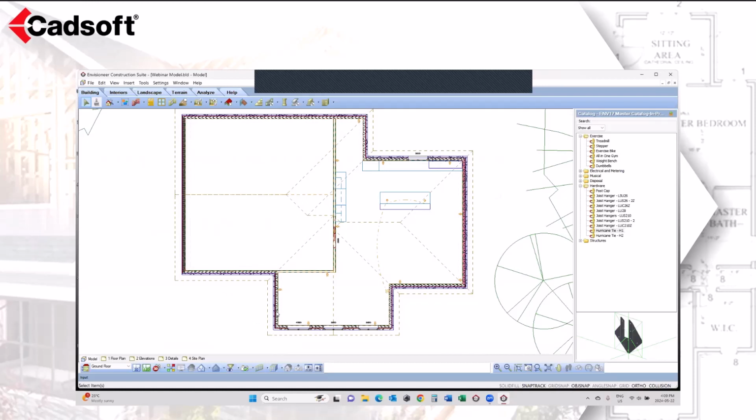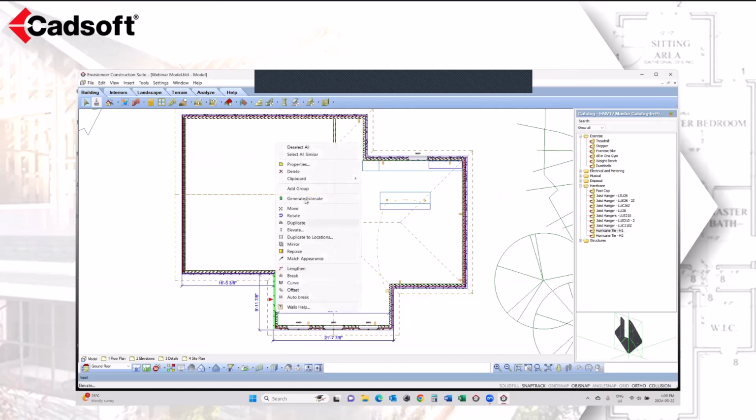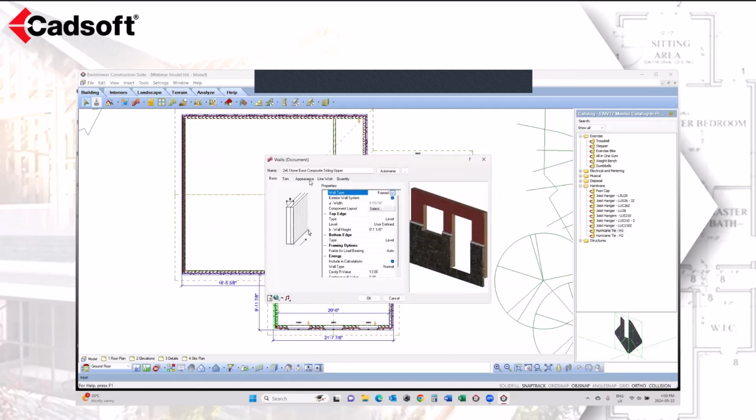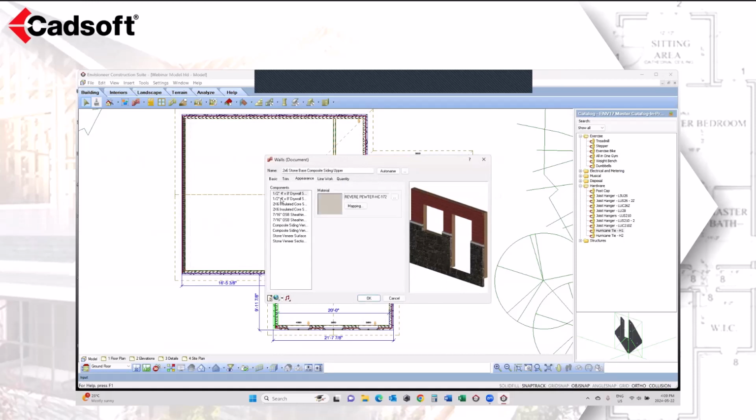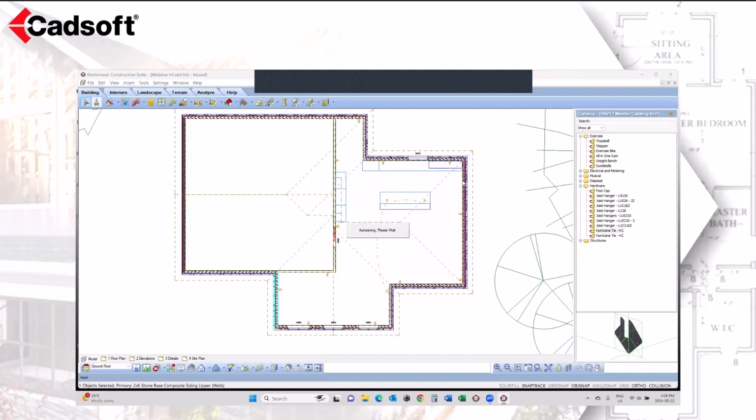And if the wall itself, properties, and appearance, and my component there, it's the core wall, oops, line work, the core wall there can have a background color. I can make it magenta. So I've got magenta going there. So each one of these can have a color, okay? And you can see the color appearing in there for us. So yes, it appears in plan view and it appears in our sectional views as well.